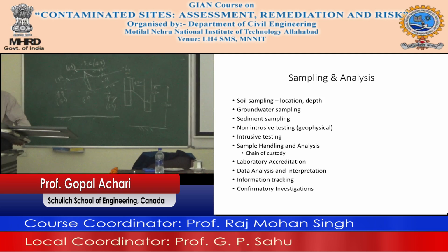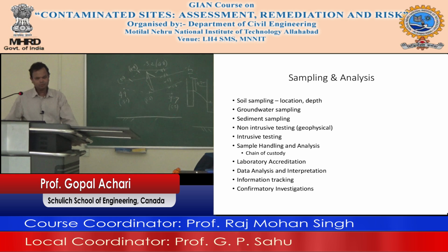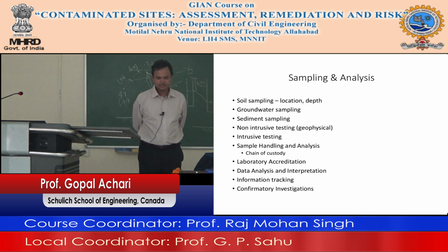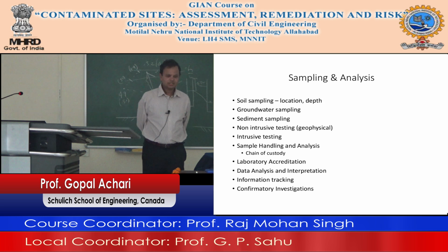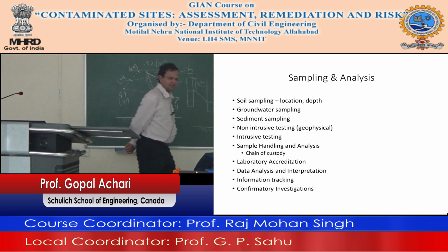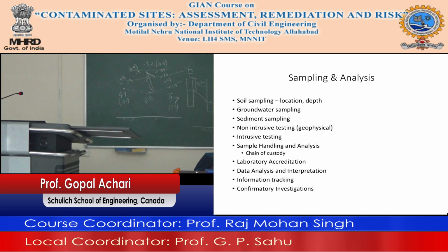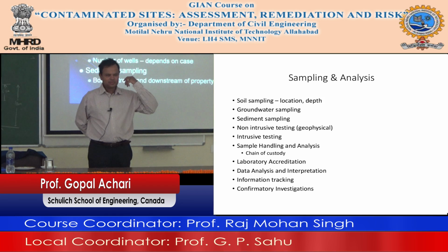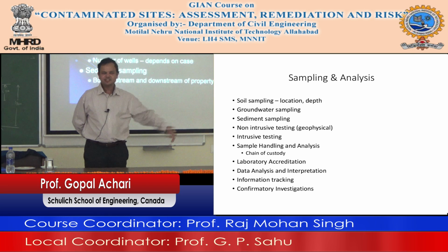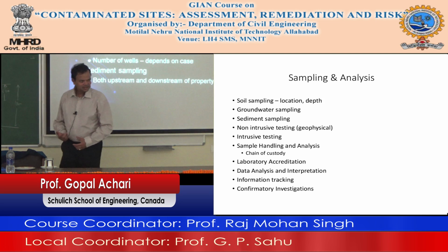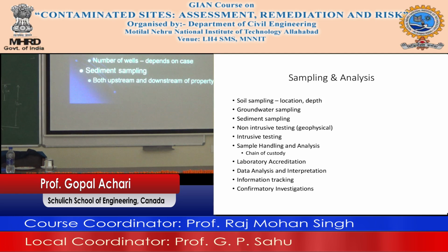Sediment sampling. You should sample both upstream and downstream of the property. If there is a little creek or a small water body flowing through your site, you should sample upstream. Why do you need to sample upstream? Because you want to find out whether the contamination is coming from somewhere else or is a problem of that site. If it is coming from somewhere else, it is somebody else's problem, in which case you have to chase the other person down. It's not a problem that you have created.